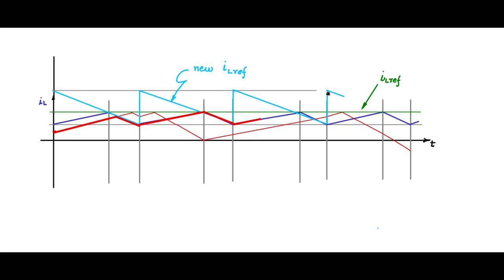So current control with slope compensation will give you the best results, where even if there are errors, the errors will be removed within a cycle and the system will be stable. This can also be proved mathematically, what I have just shown by graphs. You can refer to literature on DC-DC converters or any of the NPTEL courses on DC-DC converters.